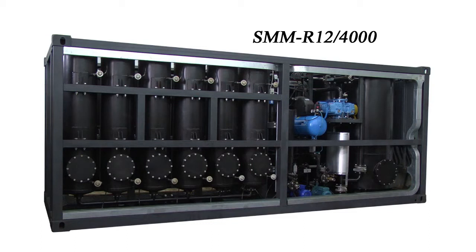In some cases, the whole oil volume must be heated to above 110 degrees centigrade, then mixed with sorbent powders, settled and filtered, which is a lengthy process. Additionally, most of the sorbents are not recoverable and require further storage and disposal.